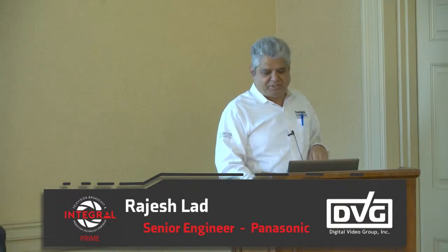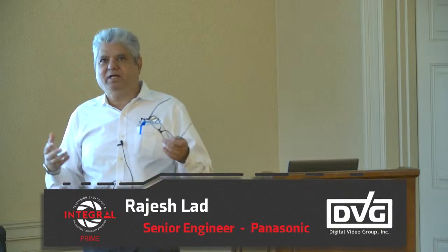So latency was also an issue slowly. SDI latency was the minimum. So then came our PTZ camera with the RTSP stream. The HE50 was our first camera with an RTSP stream. It was just providing an RTSP stream. Now we have H.264, H.265, 4K, RTMP, SRT, MPEG-TS, all kinds of streams built into the camera for encodings.